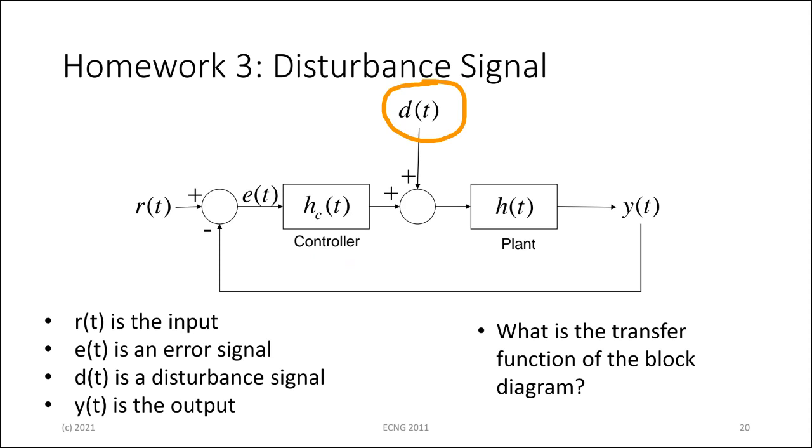So how do you simplify a diagram like this? You have two inputs basically coming in, and one of them is the real input. This is the real thing that we want, and this is the other one that happens incidentally, but we have to cater for it, right? The lightning, the voltage spike, the loss of a signal, for argument's sake, a malfunctioning device, all of those things. So we've taken a system and we reduced it to two sets of blocks. One is a whole control system inside somewhere, and one is a whole plant outside somewhere.